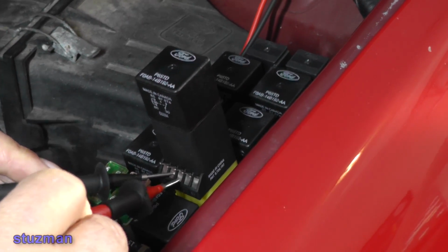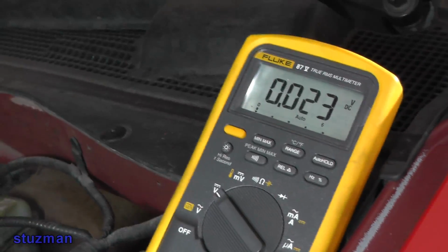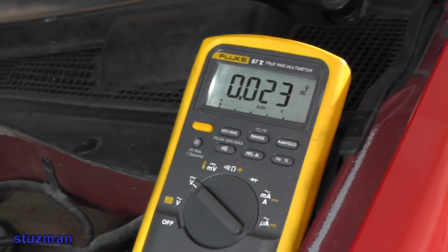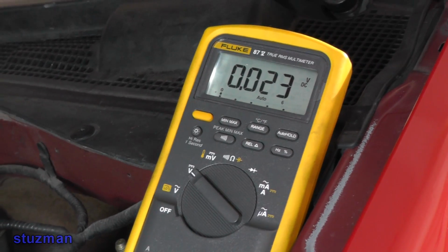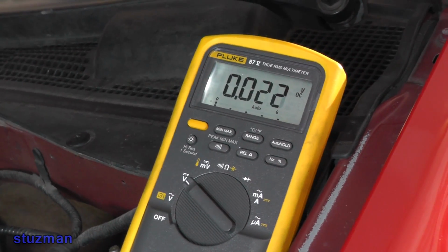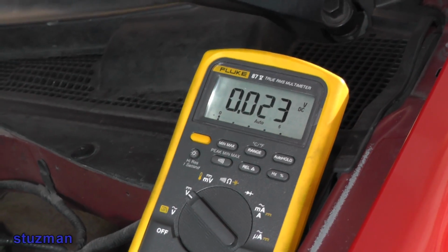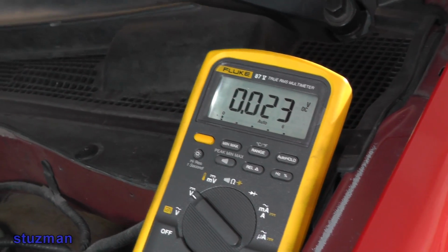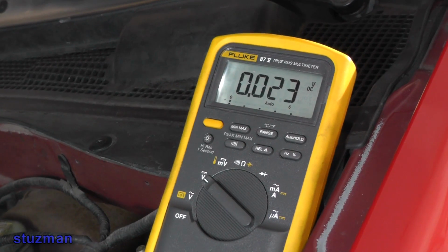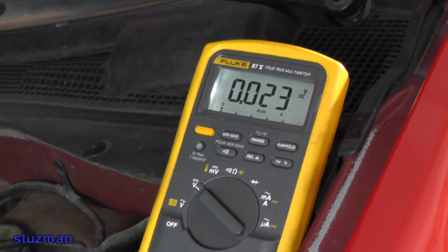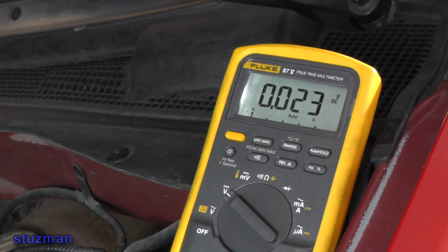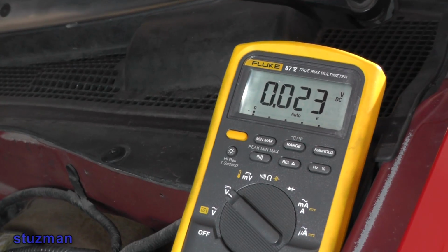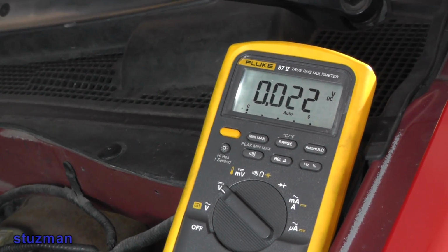All right, so here are our two terminals right here, and I'm looking up there and we've got 23 millivolts. Is that good? That's very good. For a relay that is 17 years old, and I doubt very seriously it's ever been replaced, this is a very good contact and therefore a good relay. Okay, let's get a brand new relay and put it in there. Let's do another test and see how that one looks. And remember, the closer this voltage is to 0, the better your relay contact is.